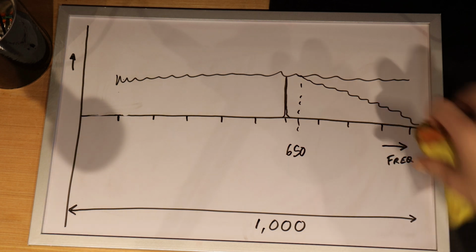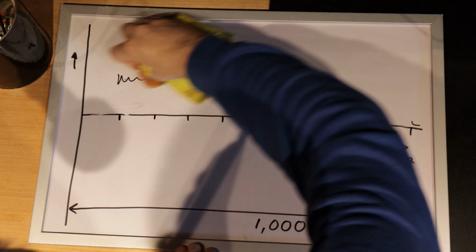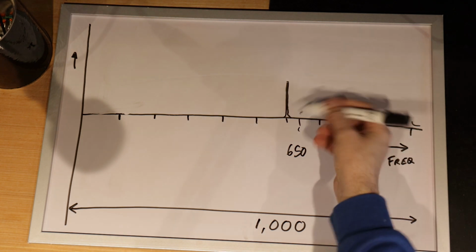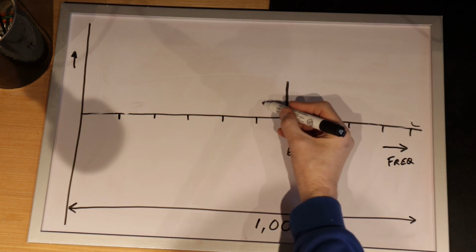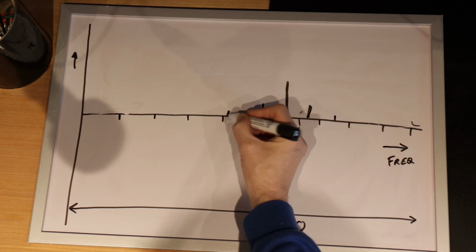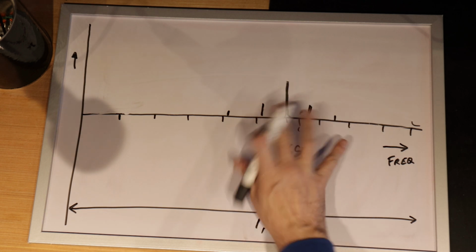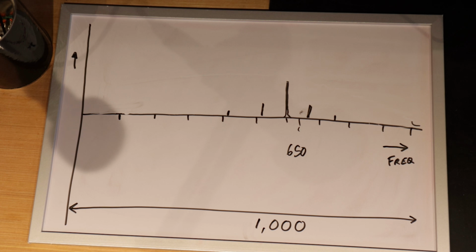Another thing would be harmonics. So we have a signal coming in, and we're getting spikes either side of the main signal. These are harmonics, and again, that might lead you to knowing what the fault is or where to look. This video isn't going to be about what to then do with it. It's simply to demonstrate the differences between these devices.